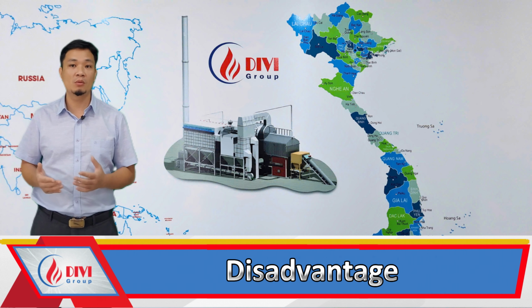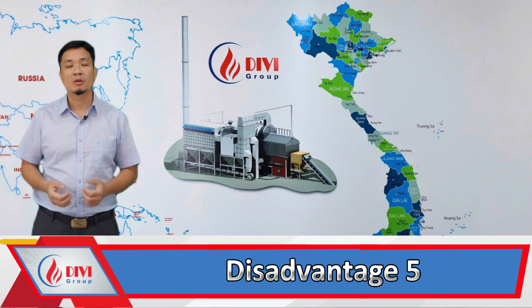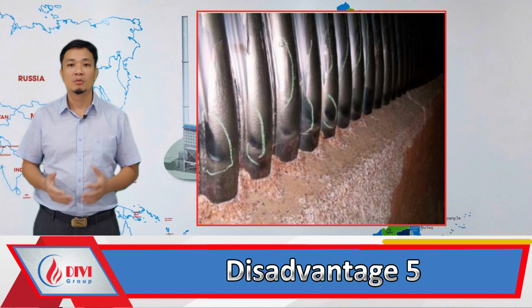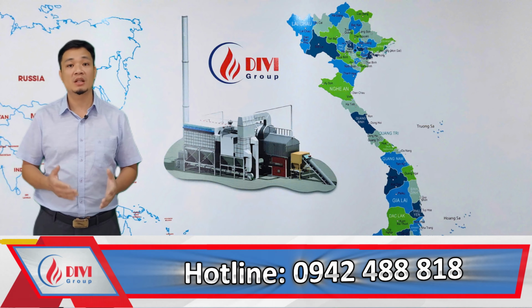Disadvantage 5. Quartz sand is highly abrasive. Prolonged exposure of boiler water tubes to the fluidized bed material can cause accelerated erosion and lead to premature tube failure. We've now covered 5 disadvantages of the fluidized bed material.